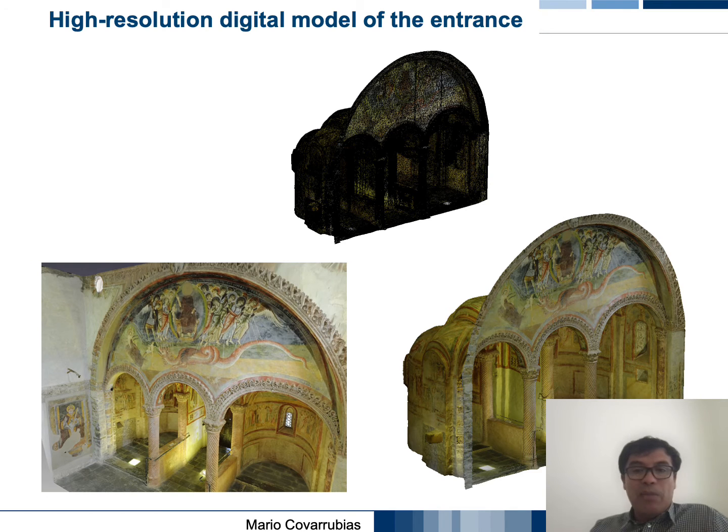The camera lens system was calibrated with an independent photogrammetric project to estimate reliable calibration parameters, which were fixed during the photogrammetric reconstruction. Data acquisition for this model took about 15 minutes, whereas processing was carried out in a few hours. No manual correction was carried out on the resulting 3D models, except the manual refinements of the external edge using geometric wrap, as can be seen in this different image.